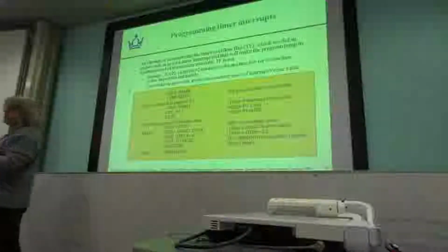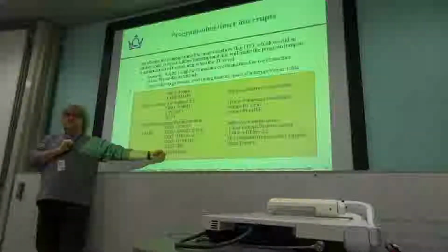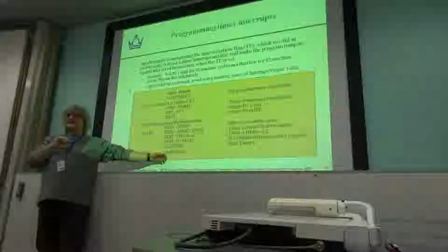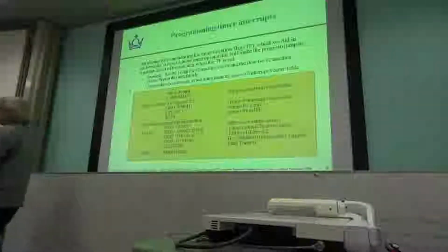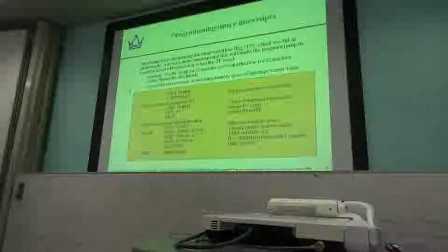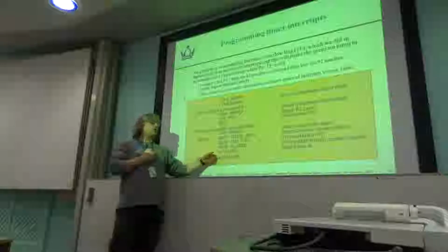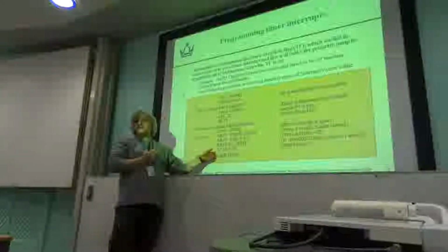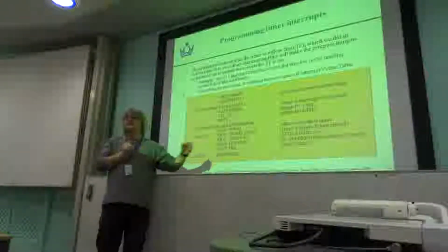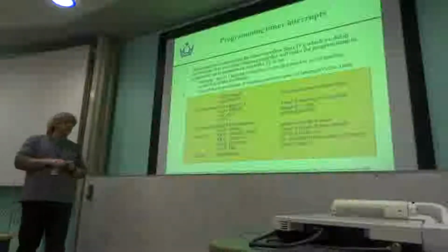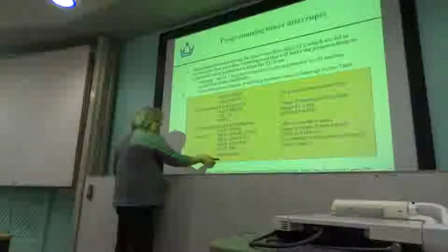So there's a couple of things there. One is we're not testing the flag. That's done automatically. The other thing, you didn't see me manually saying clear TF0. When we've been doing polling before with the timers, we've had to clear the flags. If you use the timers using interrupts, the interrupt routine itself will automatically clear the flag for you. So you don't need to do it. If you do, it's not a problem, okay? So you can clear the flag if you want to, but it's not needed anymore. So we would then basically come out of this interrupt routine, and then we would come back to everywhere in the main program and sit there again.